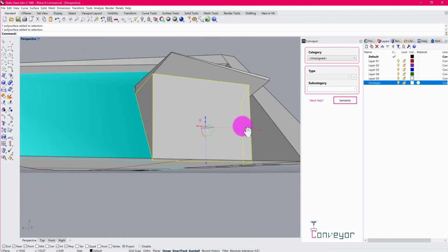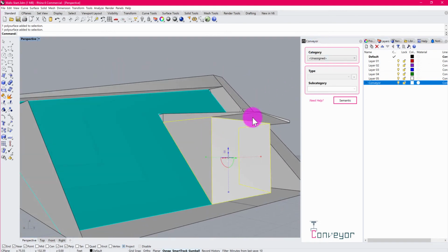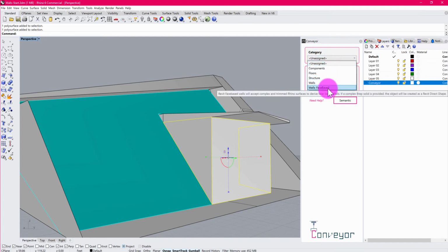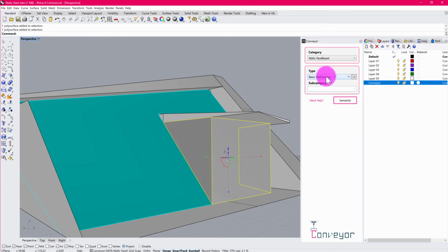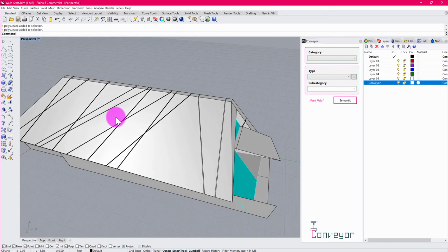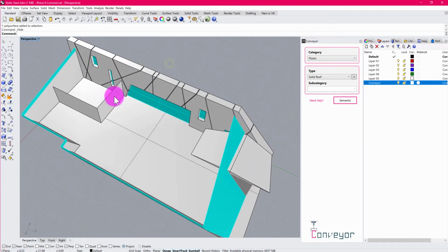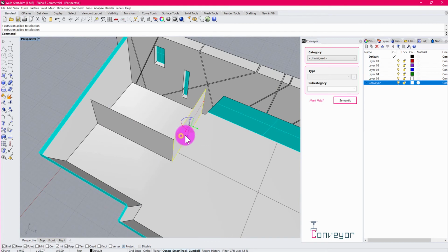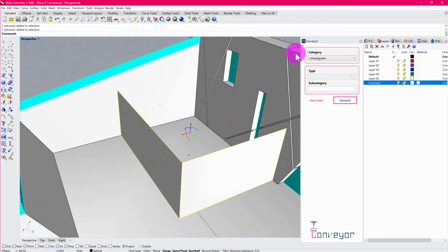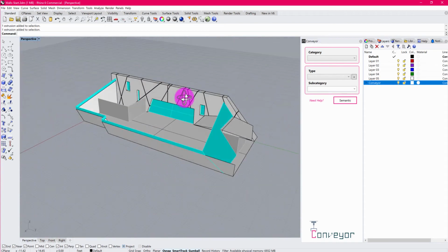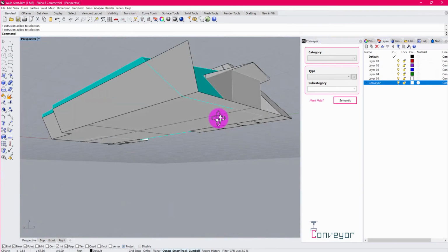I have this poly surface here. This will also want to be a wall object. So it's a poly surface. It's got some irregular cuts. I'm going to make this wall face-based as well, and I'm going to give this maybe the generic wall 6-inch classification. And then I'm going to go ahead and hide my roof here, and I have two other elements here. There's two extrusions. These are really simple walls, so I can go in and select those. I'm just going to give those the wall category, and I can keep that the basic wall generic 5-inch.